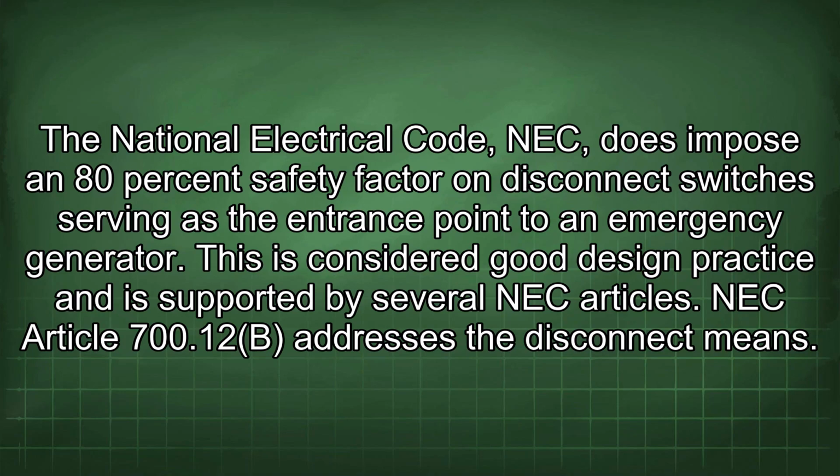The National Electrical Code (NEC) does impose an 80% safety factor on disconnect switches serving as the entrance point to an emergency generator. This is considered good design practice and is supported by several NEC articles. NEC Article 700.12b addresses the disconnect means.